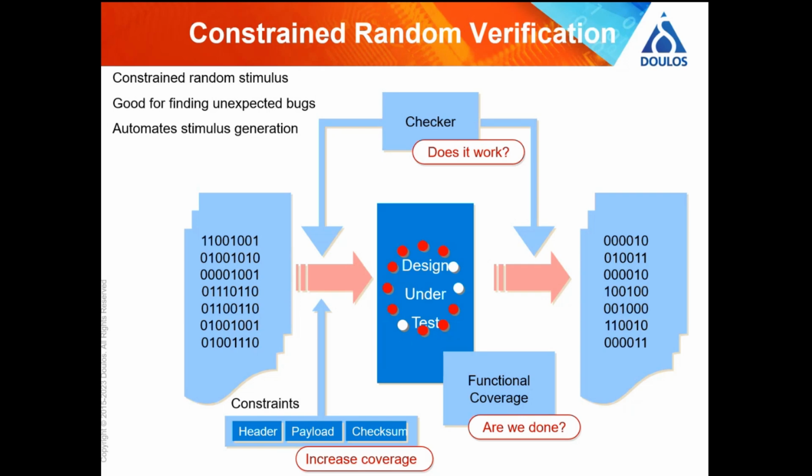More things will be tested, but you'll probably still have what are called coverage holes. So you would then look at, perhaps, why have I got this coverage hole? Oh, it turns out that I'm never generating this kind of CPU instruction, or I'm not accessing that part of memory, because the probability of that thing being generated is too low, or possibly literally zero. And so you would change the way that the random stimulus is being generated. So you've got this iterative process going on here.